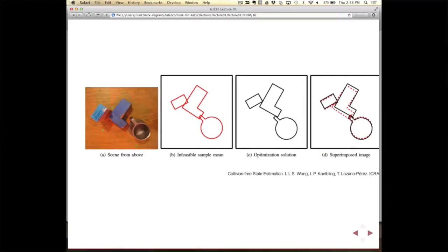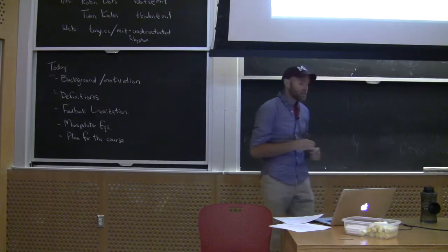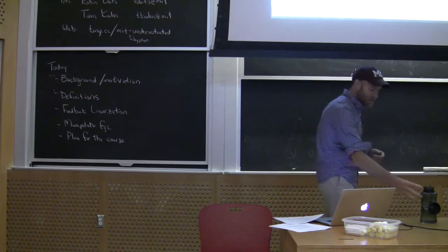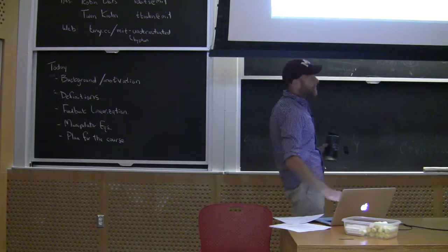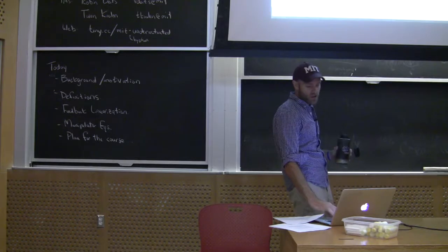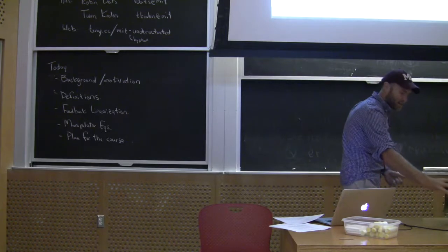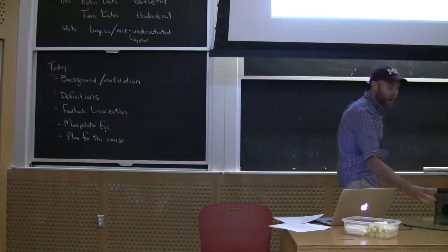One of the things he likes to talk about is the fact that most estimators that just use, let's say, a Kinect or a laser scanner in the head and look at point clouds off an object and try to estimate where the object is, have this annoying property that they'll give you some probability that the object is, let's say, in penetration with the table, right? It's stuck through the table, or multiple objects. Most of the estimators we come up with right now have things that are in collision, right? And his work here was trying to take them out of collision, okay? But they also have this problem that they'll often predict that the cup is floating in the air, or it's like this, or it's like this, okay?